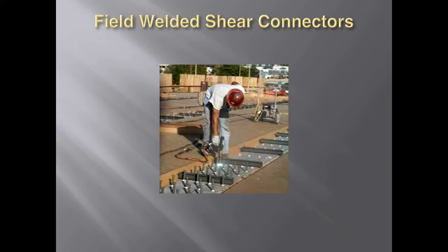The important thing is, after they do the actual installation, the procedure itself, going through, they'll weld a couple to the top of the girders. We'll bend them over to make sure that they're not breaking, and then we'll let them go. The big thing to remember is those guys need to break the ferrules off on the bottom of these studs. It's a ceramic ferrule that has to be there. Once it's installed, they can knock that off.